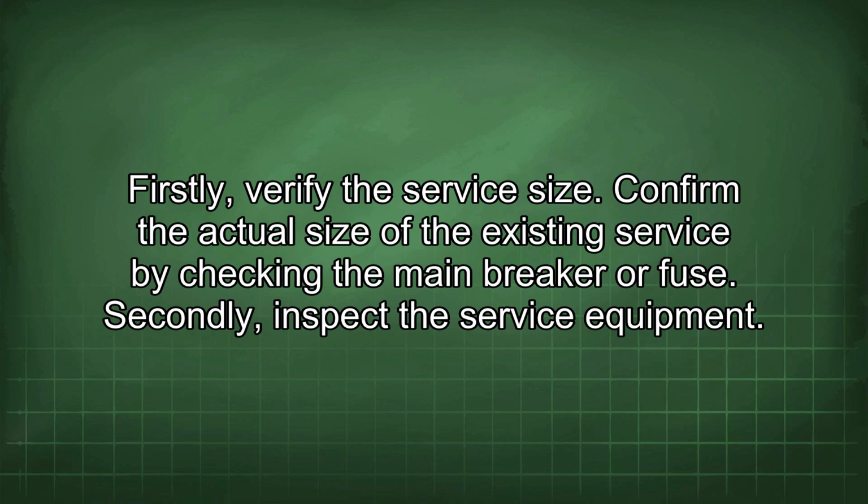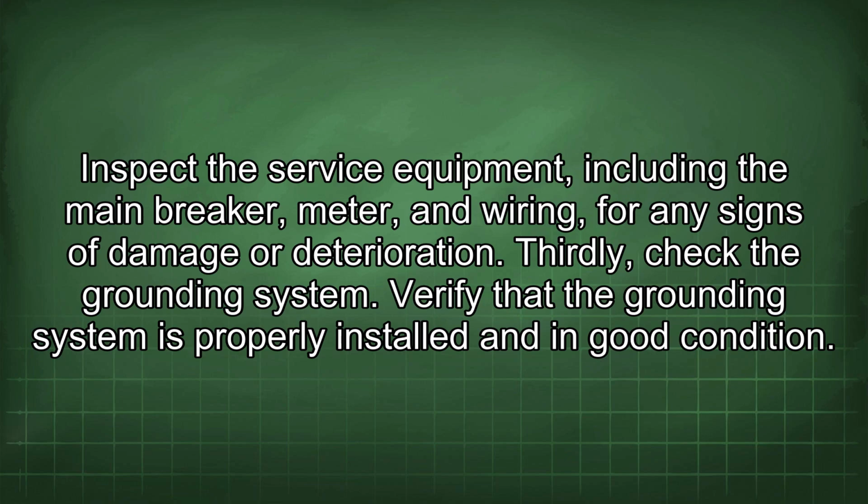Secondly, inspect the service equipment. Inspect the service equipment, including the main breaker, meter, and wiring, for any signs of damage or deterioration.